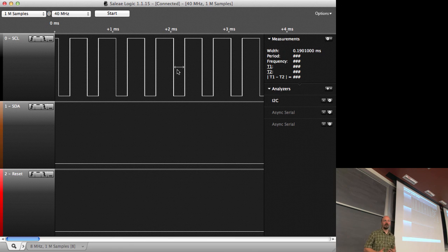So then how fast do we have to sample in order to figure out what's going on with our signals? More than twice, exactly. We're going to look at that. That's what's called the Nyquist Theorem. Nyquist says that if we sample a signal more than twice its highest frequency content, then we can reconstruct it entirely. Okay.